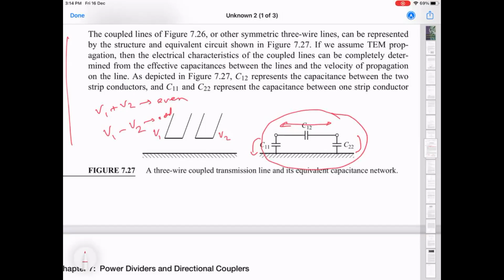So for example, if these two transmission lines were far away and they had some characteristic impedance, when you bring them close to each other, what does it mean to talk about a characteristic impedance of the individual lines? Should I think about them as the characteristic impedance of the even mode or the odd mode? That's basically what's going to happen. Of course, if you take them far away, they are individual lines, but when they're interacting, you can now start talking about properties of these even and odd modes, and they have a little bit more natural meaning because you can then separate these two modes because the two modes don't interact with each other, right?